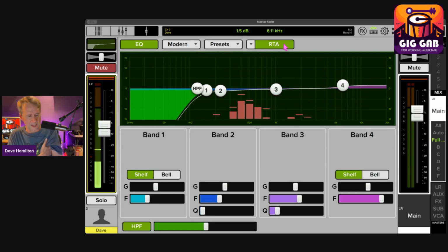I had to do it at a gig where I subbed a few weeks ago, the one where there was like this 8-channel analog mixer and they had some outboard graphic EQs. And I'll talk about what a graphic EQ is in a minute. And I couldn't trust my ears anymore. I had forgotten how to hear and relate that to a frequency, because I've gotten so spoiled by having it literally appear in front of me on the real-time analyzer. But these are good problems to have. So that's the parametric EQ, the one with different handles that you can just put where you want and move the frequency left and right, and then the gain up or down.